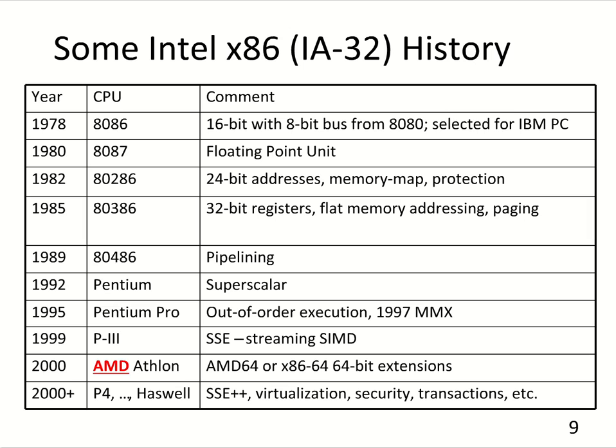There have been over the last 15 years additional revisions of SSE providing additional instructions, additional data types, and higher performance. A big change occurred in the year 2000 when AMD, who was designing compatible parts to Intel's parts through much of this history, actually introduced 64-bit extensions to the instruction set. So they extended the address width and the register widths to 64 bits and added all of the corresponding 64-bit operations to the set of ALU instructions as well.